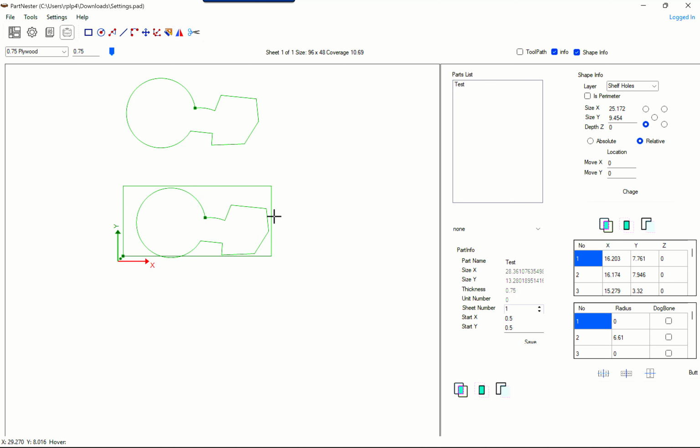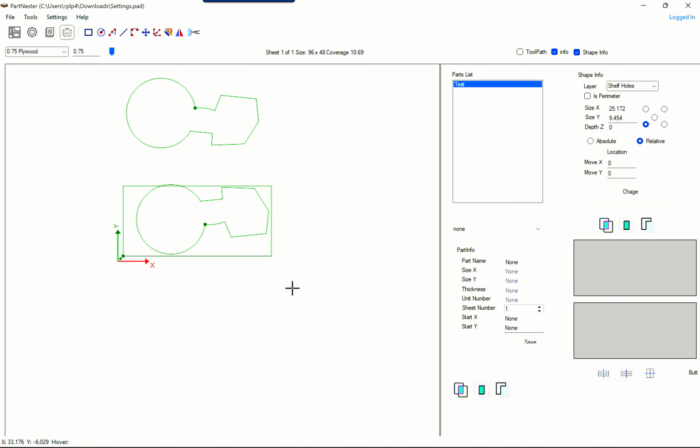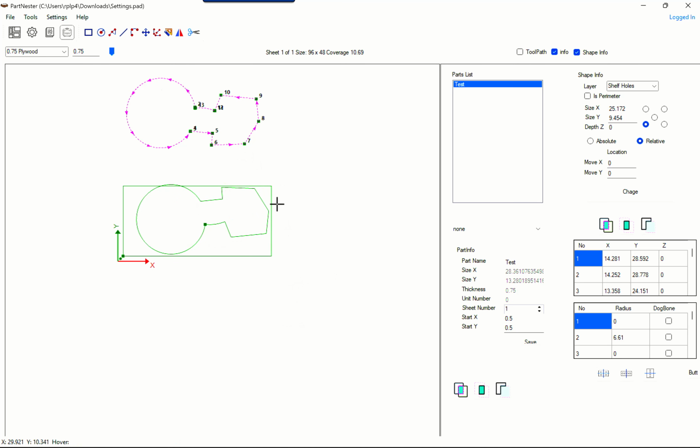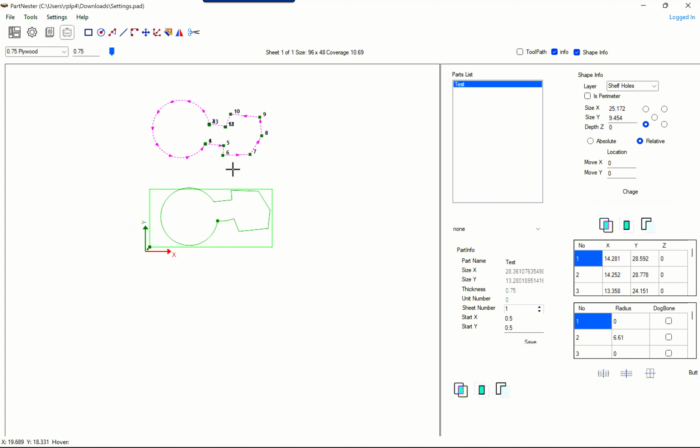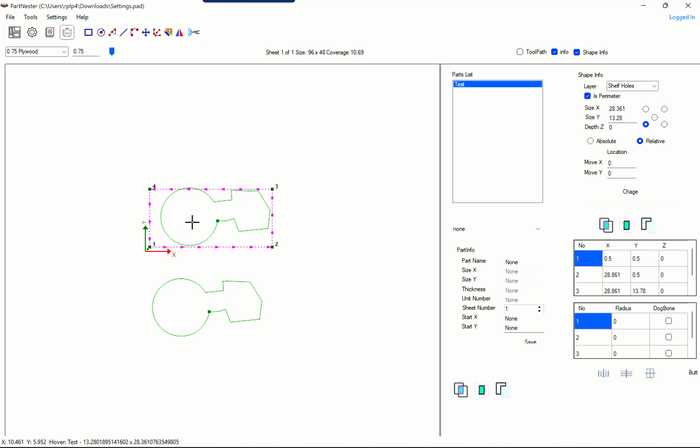I'm going to Control Z, and this time I will select the shape, holding the Y down, and we see that that shape gets mirrored in that direction. We could do the same thing for this object here. I'm going to hold the Y down and select mirror, and we see that it got mirrored down below, and it is being mirrored about the center marks of the owning shape.